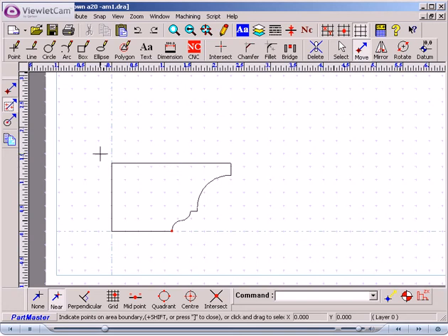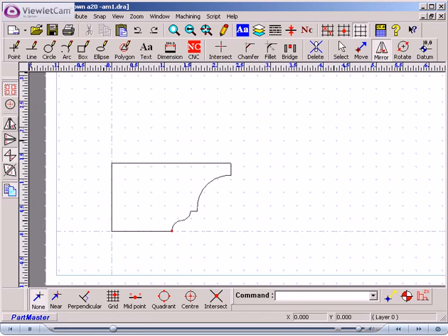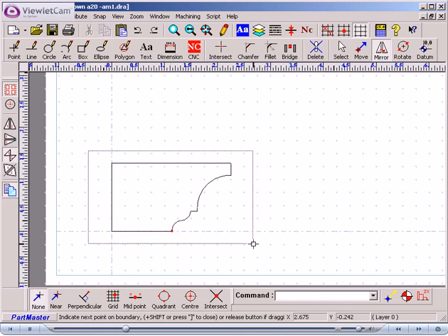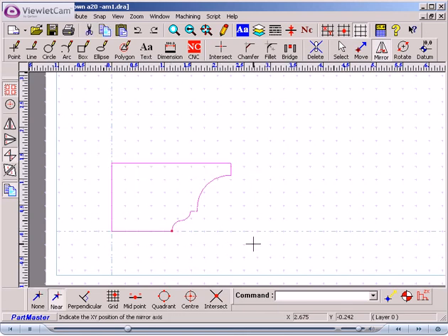So what I'm going to do now is use the mirror command to create a mirror image of this shape, and we go into mirror, mirror an area. We can mirror in X, in Y, or in X and Y together, and then the mirrored selection can either be a copy, which is what we want, so the original is left in place. So the first thing I'm going to do is just drag my cursor around the area I'm interested in and then give it a grid location. This is the point about which it's going to mirror. The actual position I'm not too worried about now.